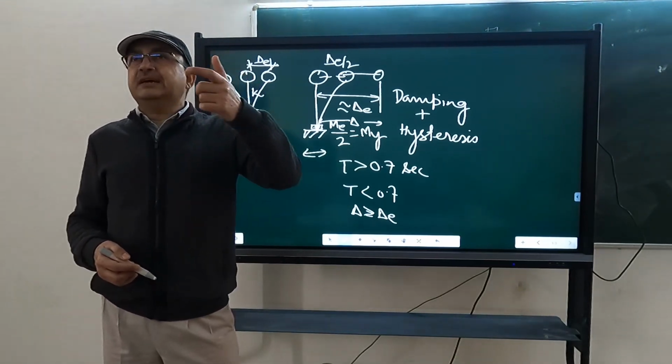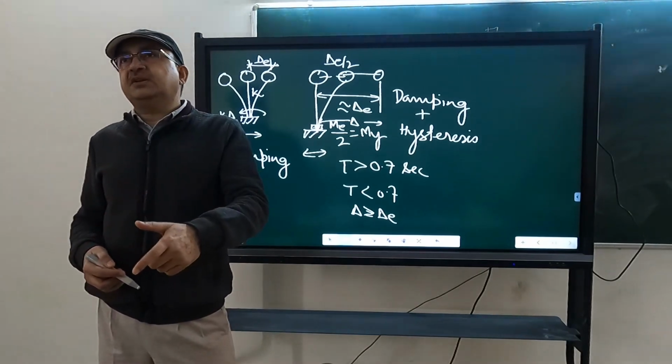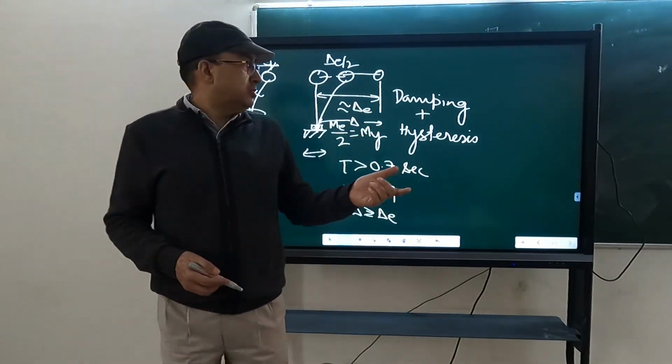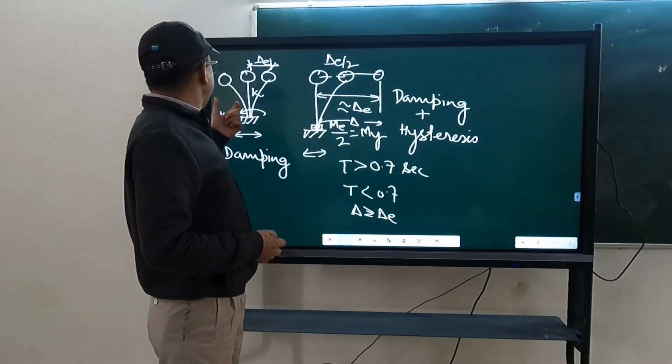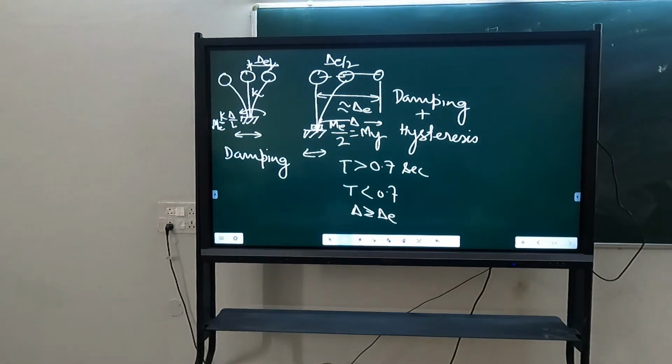The reduction in the capacity for which I have designed. Design capacity divided by the demand on the elastic structure. So that is My divided by Me. So R is 2. For R is equal to 2, can you calculate delta of the inelastic structure in terms of delta of the elastic structure?